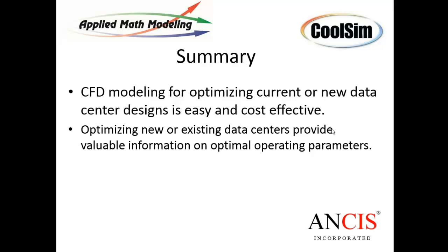Another question here, how does CFD capability adjust or accommodate for moving loads? I'm a fan of CFD, but the dynamic loads are challenging for static solutions. Well, again, as Magnus pointed out, what you do with CFD is you look at your extreme cases. We used to call them in engineering the corner cases, right? What we want to do is understand the worst case conditions, the best case conditions. What are the corners? If we know the corners, then everything to the interior of that design space ought to work. So dynamic loads, what is the worst case condition?